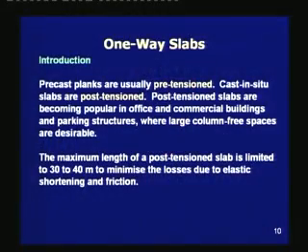Precast planks are usually pretensioned. They are manufactured in a yard under controlled environment, whereas cast in situ slabs are usually post-tensioned. Post-tensioned slabs are becoming popular in office and commercial buildings and parking structures, where large column free spaces are desirable.